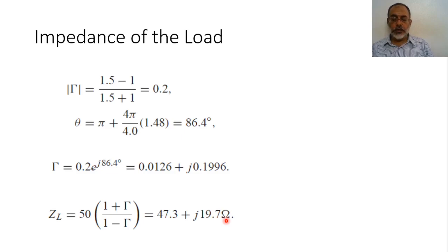So by using the results of the measurement of such a slot line, we could obtain the wavelength, the frequency, the magnitude of the reflection coefficient and the phase of the reflection coefficient. And from the amplitude and phase of the reflection coefficient, we obtain the input impedance or the load impedance. This calculation has been done numerically. It can also be done by using this Smith chart.